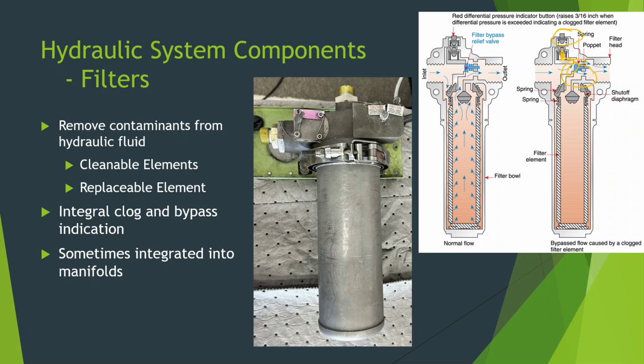Now, from a maintenance perspective, probably 9 out of 10 times when one of those popped, it just popped because of a pressure surge in the system. It wasn't because the filter was actually going bad. So the first step in our maintenance manuals, when you found one of these deployed, sticking out, is that you reset them. With the system off, you simply go up and push back down on it. It'll latch back in place.